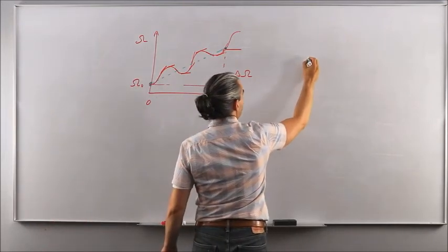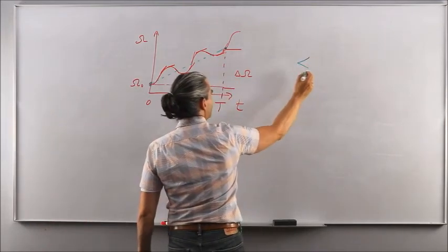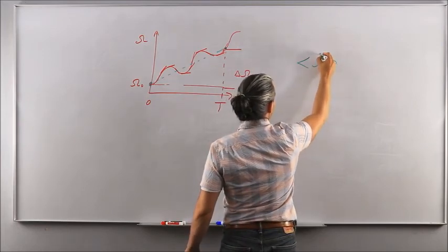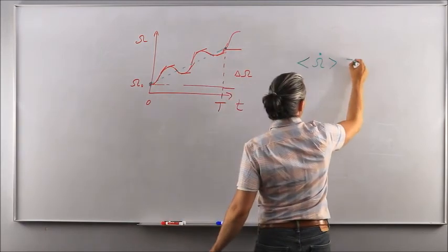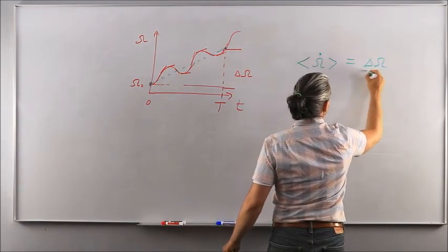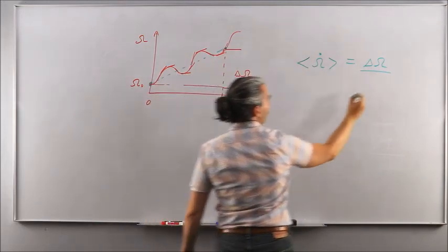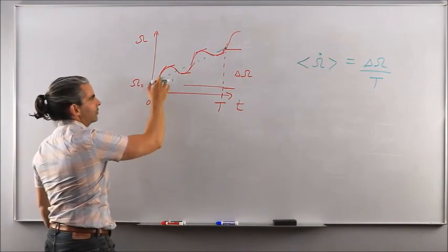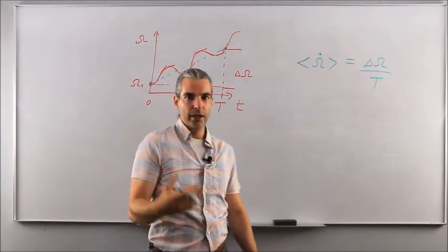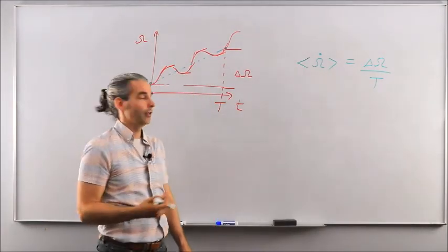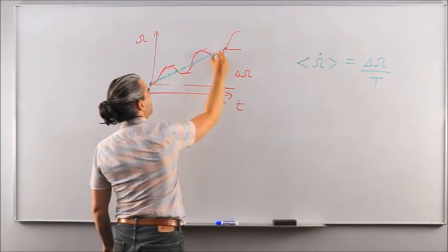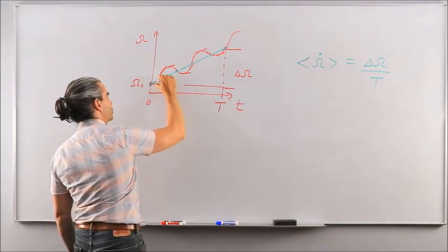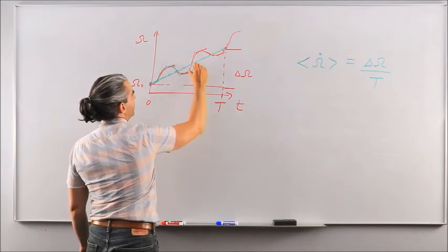And you say that my average rate of change, which is denoted by this and that with the orbital element and dot, is just your secular variation in radians over 1 orbital period in seconds, okay? So it gives you a rough idea of how the orbital element is changing as a function of time by averaging the slope as a constant instead of looking at the instantaneous change, which is what the GVE are giving you.